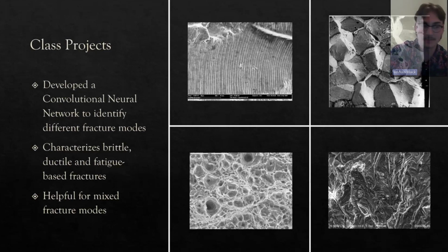Maybe I thought that this fracture was brittle, but it ended up being a fatigue-based fracture based off of some beach lines that you see here, some striations. And if we look at that picture again after inserting it into the algorithm, now I see these beach lines. It was a very interesting project to work on. It was a very intense one, but it's something that was very interesting for me to learn.